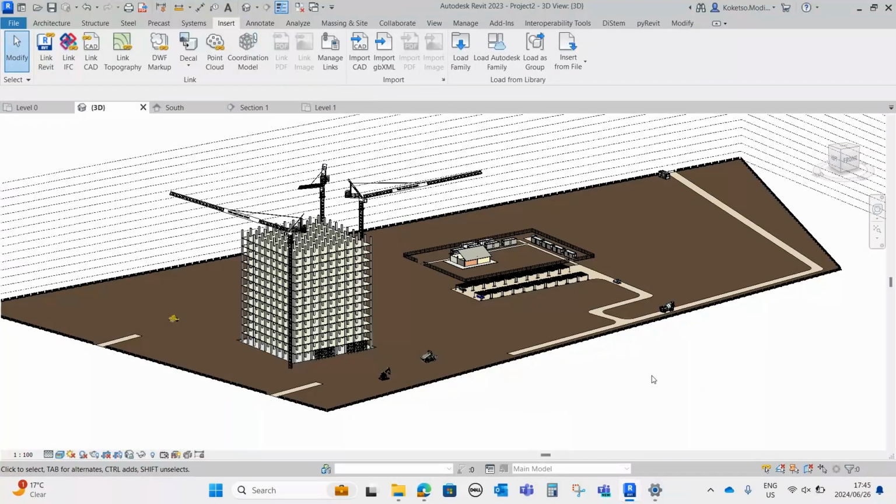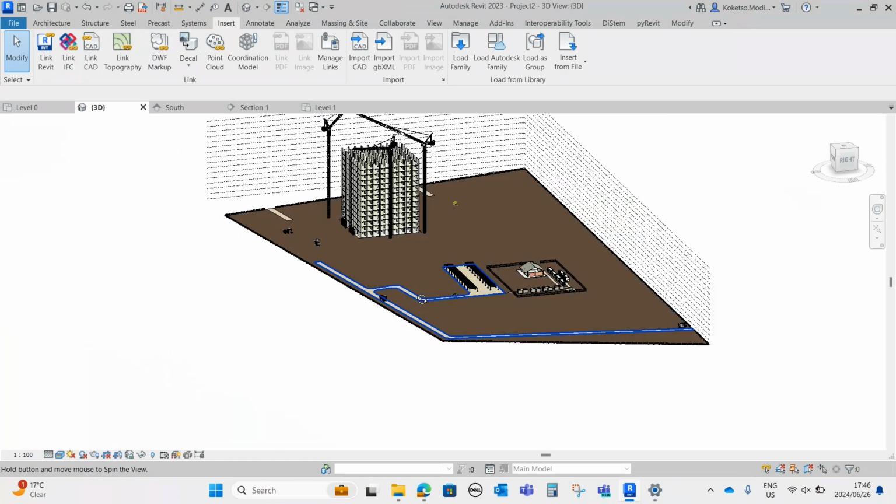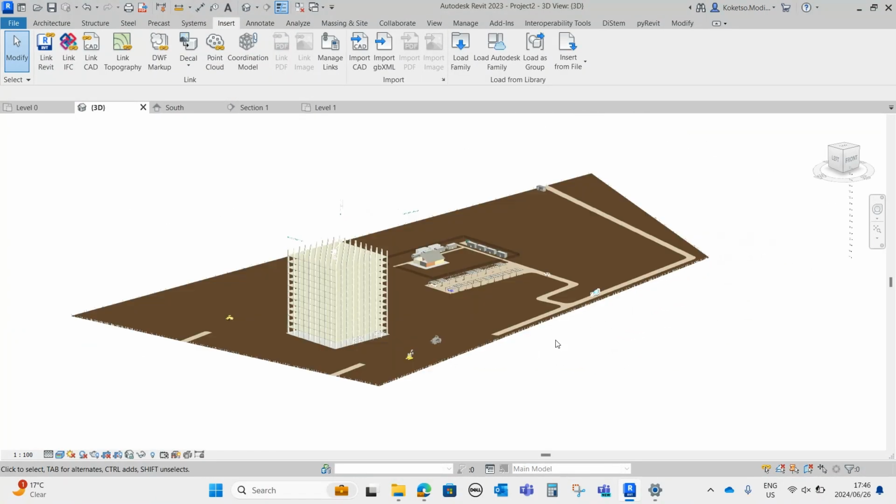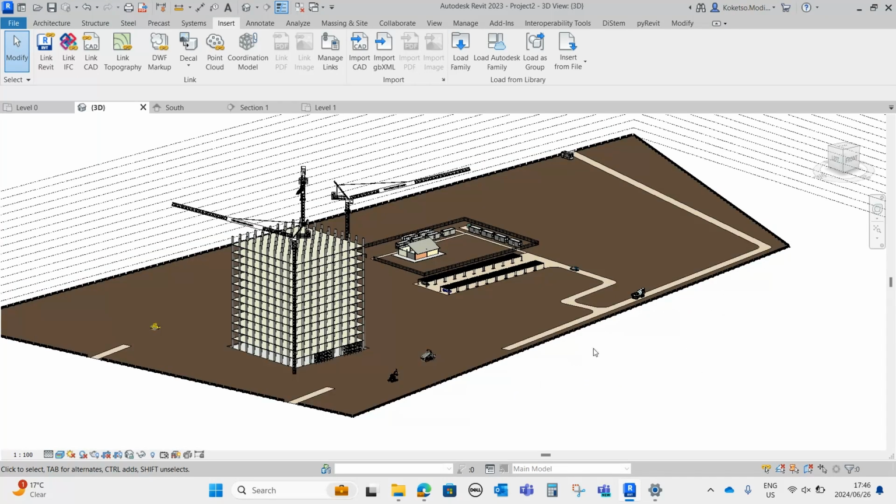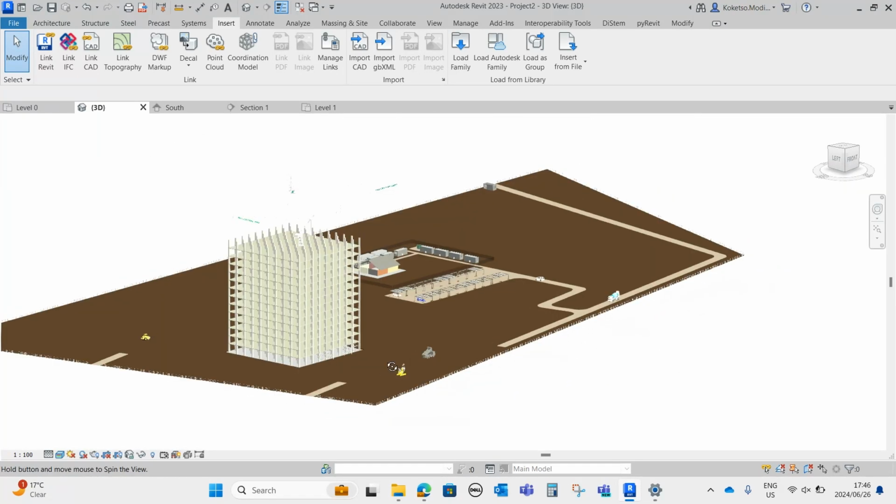You guys can add as many components as you like, and then you can make it much more intelligent by applying marks on certain Revit families, and then you can take it to Navisworks and do high level of detail 4D BIM or construction sequencing or construction planning. Yeah, but this is a great starting point, if I can put it like that. So it's very much representative. You can take it much further, but please stay tuned. We definitely gonna take it much further on the upcoming tutorials.